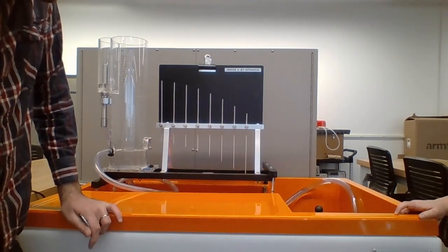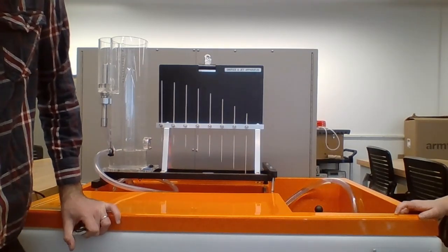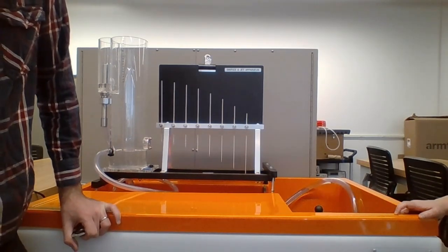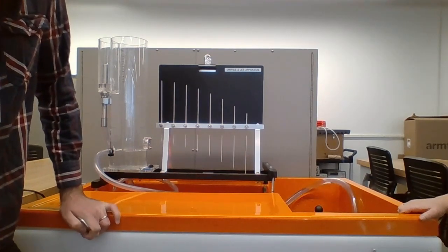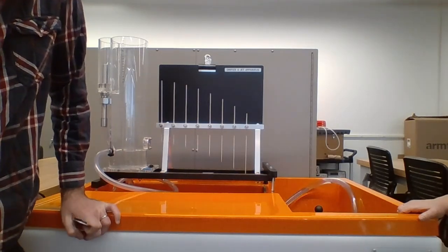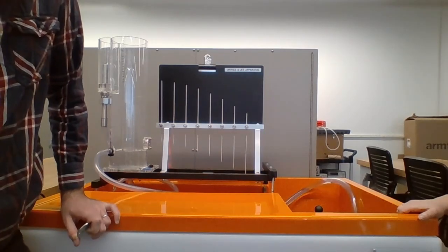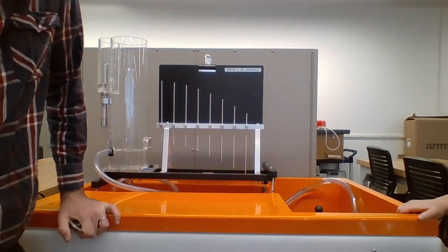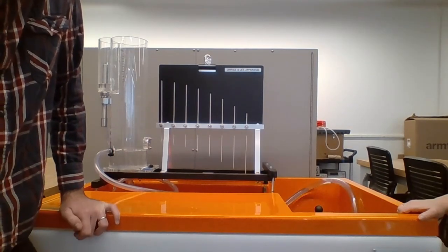And essentially we can treat that jet of water as a projectile, and then use our projectile motion equations from Physics 1. We gotta remember those. We can back calculate what the initial velocity of the water is, and then using that initial velocity we can come up with our parameters for the geometry of the orifice. So I'm going to turn the machine on and you can see how the tank fills up.